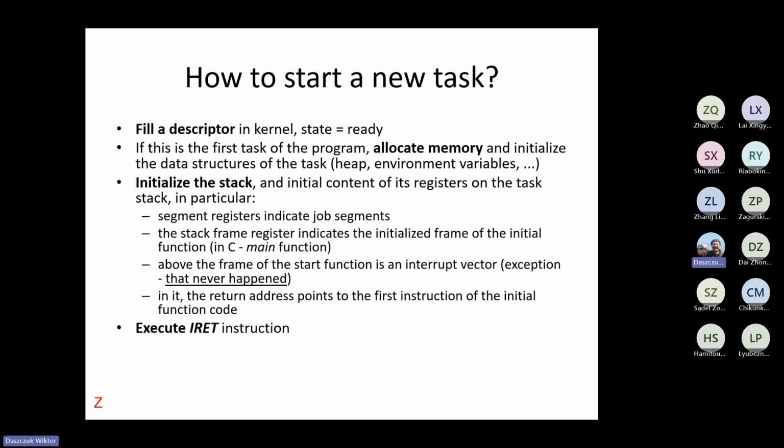Okay, we have the stack and the rest of the memory if it's the first task in the program. So we should start the program. How do we start the program? We build on the stack the set of empty registers and perform the IRET instruction. We return from the interrupt, which never happened.